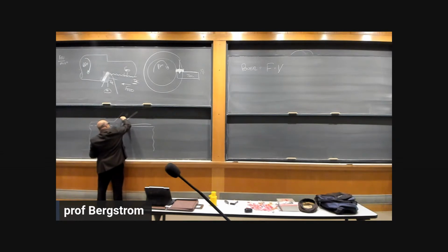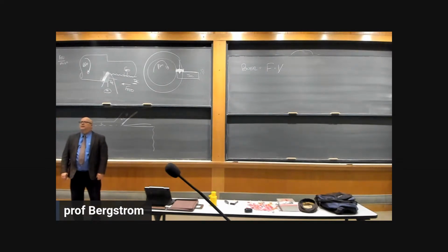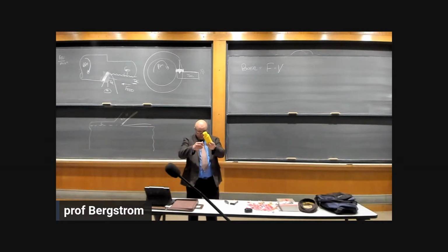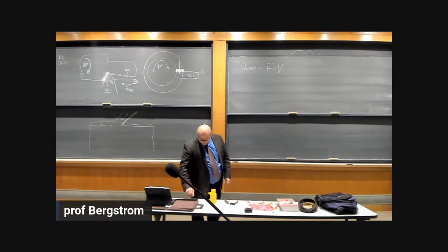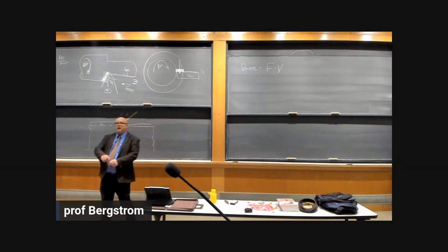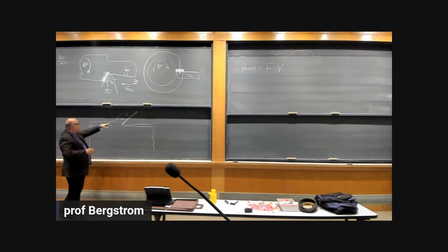And we'll put a t2 there. That's the thickness of the chip. They won't be the same as each other. Is that fair? Maybe they are the same as each other. All right, maybe. No. If there's a cutting force, they won't be the same as each other. Only if they were not actually part of the same material to start with could they be the same. Then it would be like we were just unwinding a spiral. All right, so we've got our uncut chip thickness, we've got our chip thickness.